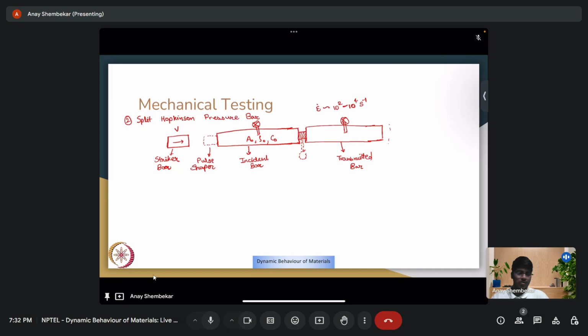So, if you look at how stress varies as a function of time, you would have something like this, some small oscillations. These, if you remember, are the Pochhammer shocks, and they are related to edge effects associated with the rod. The rod has a finite thickness, it's rather particularly thin, and there will be some edge effects associated with that.